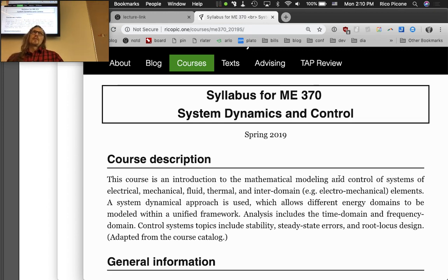So again, remember that we're specifically focused on lumped parameter modeling in this class. So we're going to treat a pipe as like one or two lumped parameter elements, like a fluid resistance and a fluid inductance is one way to describe it. Inertance is what we'll call it.